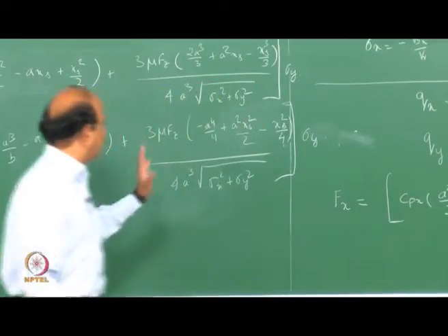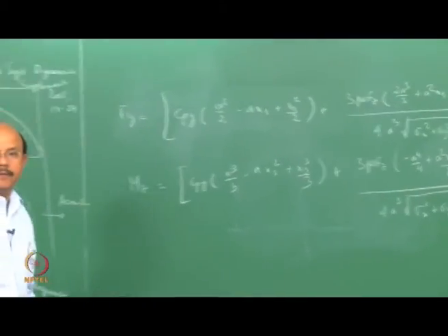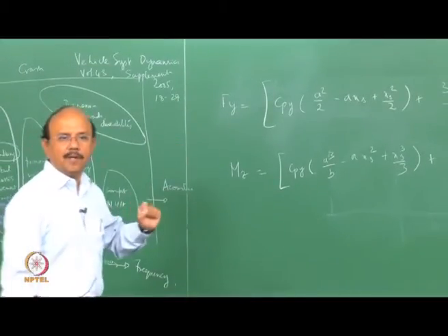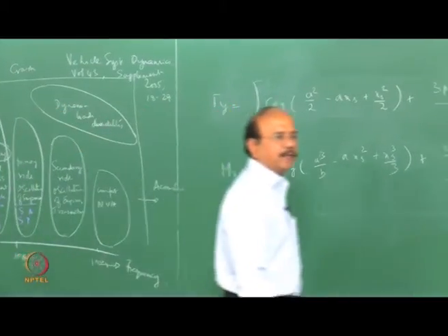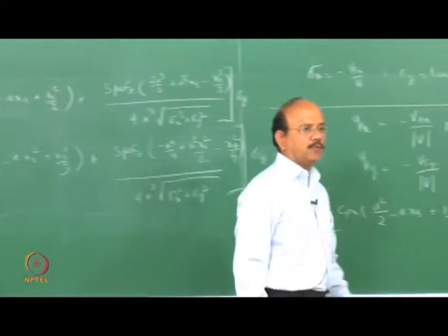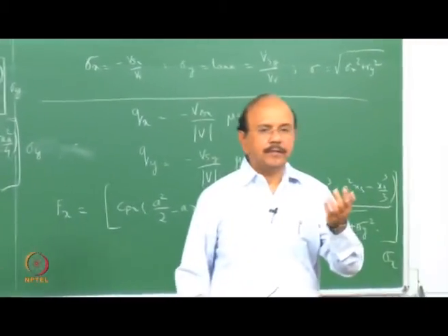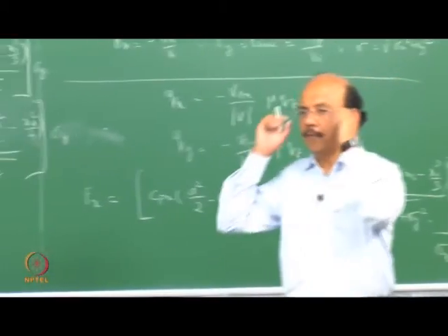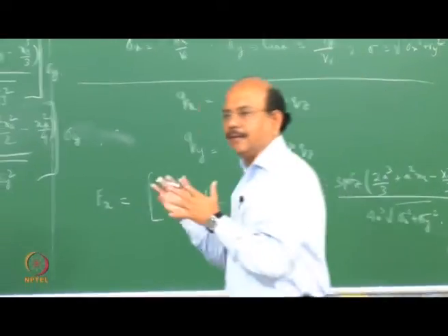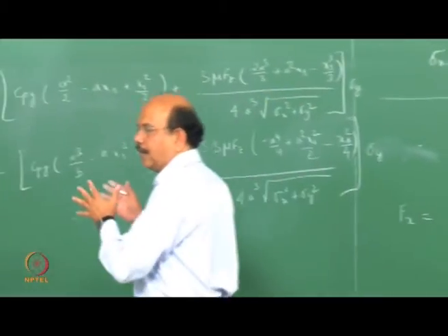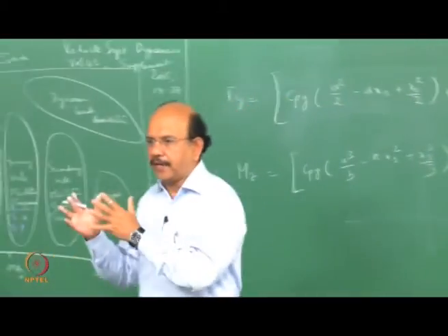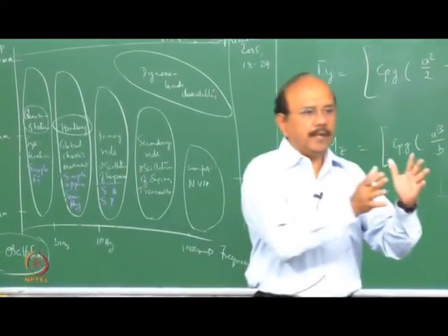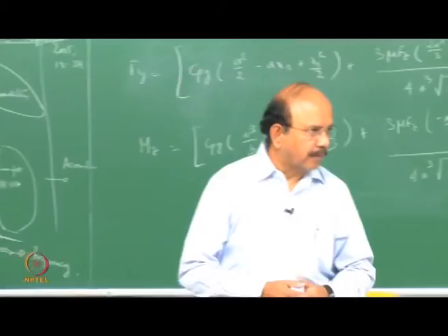Yeah, essentially, how did we get this? We got it in a similar fashion as we did before. Remember, how did we get this kind of expression for a longitudinal force? We looked at the deformation. You remember that we looked at the deformation. We looked at how much the tread, which was a brush, deforms as you move into the contact patch.